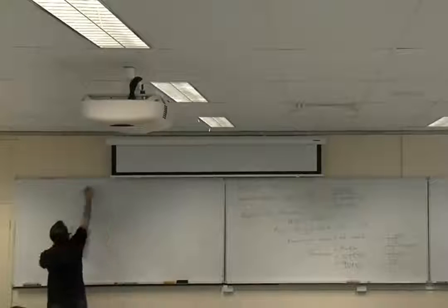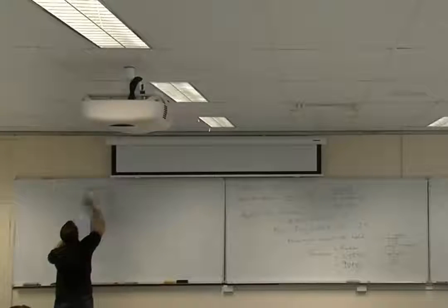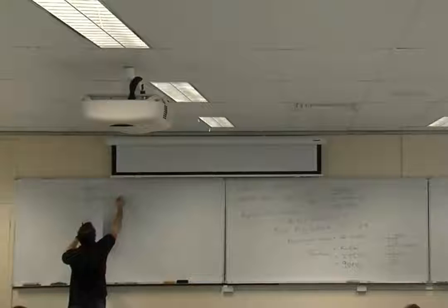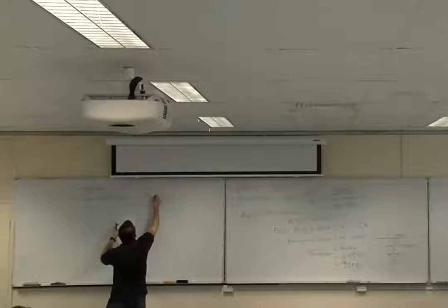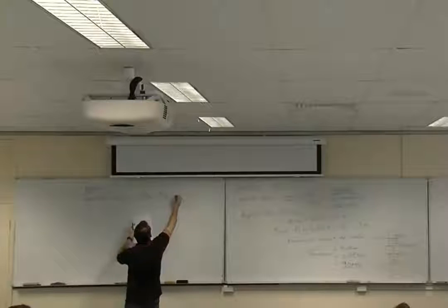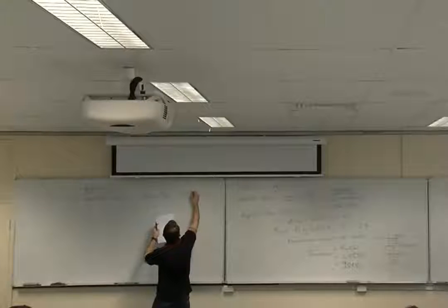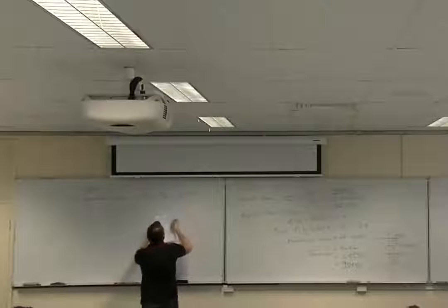Alright, the last one is our notch. Same layout, so nominal stress: sigma nom equals P on A. P doesn't change, so 45,000.